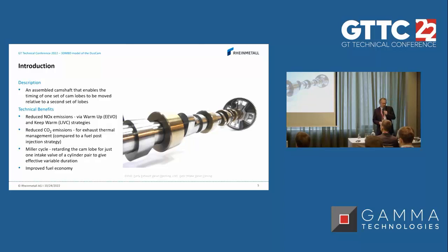NOx emissions can be saved through targeted timing of the valve. Thermal management strategies can be implemented to reduce CO2 emissions. The Miller process is realizable. And finally, all these measures have a positive effect on the fuel consumption.